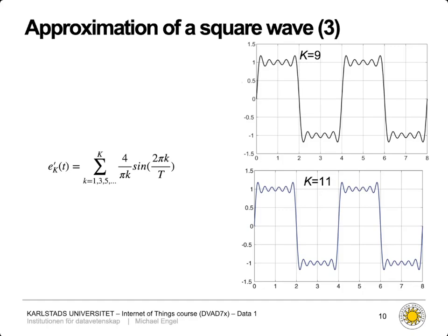And this is also what you see when you look at a rectangular or square wave with an oscilloscope. You see these signals are over and undershooting for a bit, so they won't stay at the exact equal level of 1 and -1. And there's also no perfect vertical line going from 1 to -1, because that would mean you could transfer charge infinitely fast.